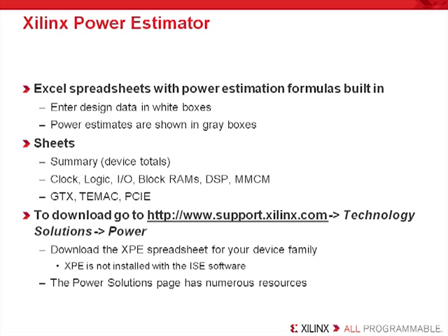Now, this is a good time to remind you that the power consumption of each resource is significantly different. In fact, ideally, you'll target the dedicated hardware resources as much as possible, rather than use just the CLB logic resources. Now, this is because the dedicated hardware is optimized for minimal power consumption as well as high speed. So be sure you're getting the correct hardware resources inferred by your synthesis tool, since it will choose which resource to map to based on your HDL coding style and any instantiations you place in your design.